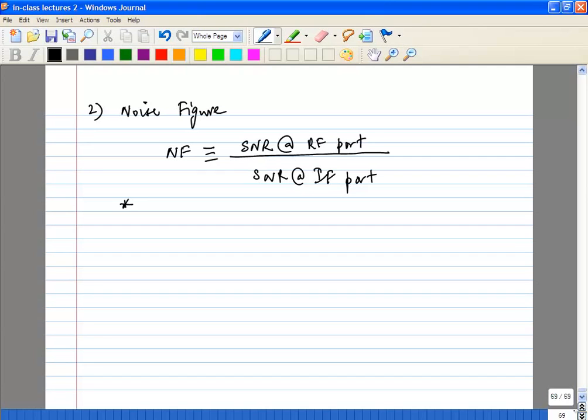You can just do it the normal way, the way you would calculate your noise figure. But just keep in mind there are a couple of things you need to know, which are special to the case of mixers, which you wouldn't have encountered in LNAs. There is one case for noise figure and there is one case for IIP3. For noise figure, just remember that you have to be very careful about your image frequency. Remember we calculated how your image translates on top of your RF signal. That's why you have what is called an image reject filter, so you have got rid of all the signals at the image frequencies. Everybody remembers the image frequency.